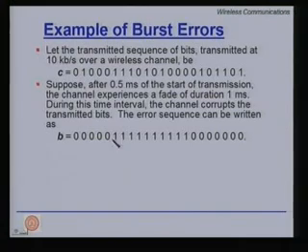So, here is the start of a fade, and the fade lasts for so long, and then the fade ends, because we know the data rate and we also know how long the fade lasts. Here this is kind of an error pattern. So, all the bits within this fade have been flipped, but clearly we do not know the fact that all of them have been flipped. If we knew it, we would just flip them back and the problem is solved.